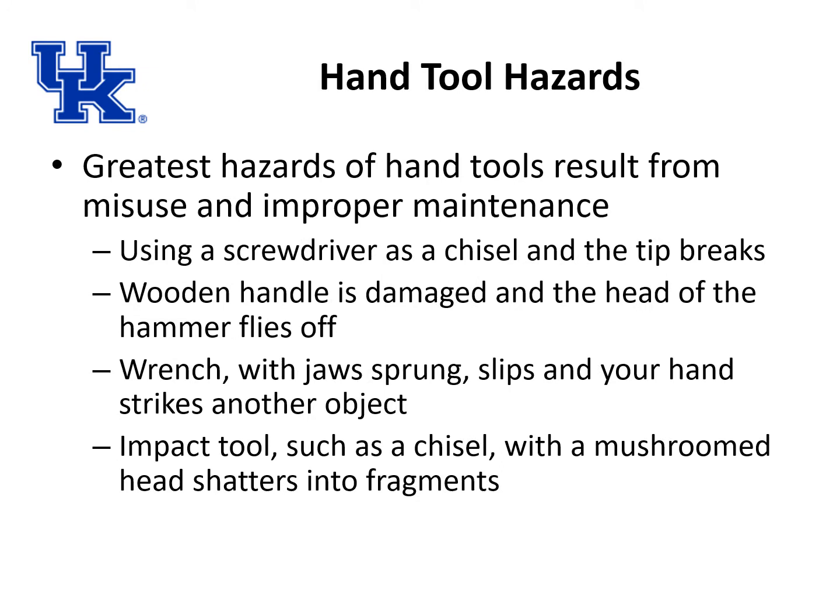The greatest hazard posed by hand tools results from misuse or improper maintenance. Using a screwdriver as a chisel and the tip breaks. A wooden handle is damaged and the head of the hammer flies off. A wrench with jaw springs slips and your hand strikes another object. Impact tools such as a chisel with a mushroom head shatter into fragments.